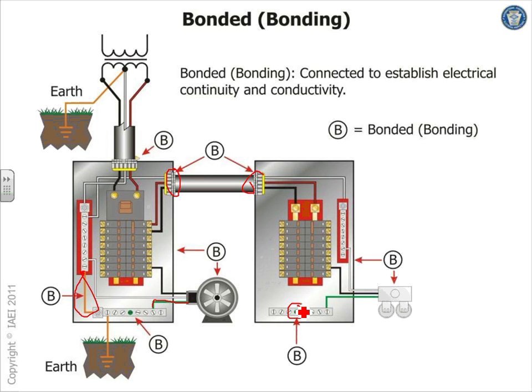Yes. Look at the conduits, EMT conduit. When you have the right connections, it can bond itself from both sides and act as an equipment grounding conductor. So it doesn't have to be either or. Yes, sir.